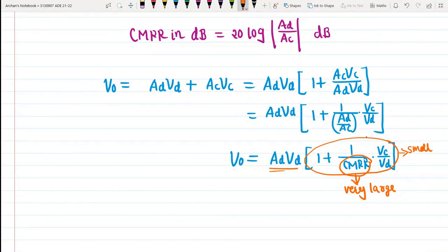And that is why this is important in analog electronics. Okay, so we require our common mode rejection ratio to be as high as possible to reject the common mode signal. Common mode signal is not desired. Okay, this is not the desired signal. It is available because of the noises and disturbances in the input signal, right? And this is the reason why it must be rejected. Okay, so with the help of this CMRR, we will be able to reject these common mode signals, right? So this is how this differential amplifier will work.